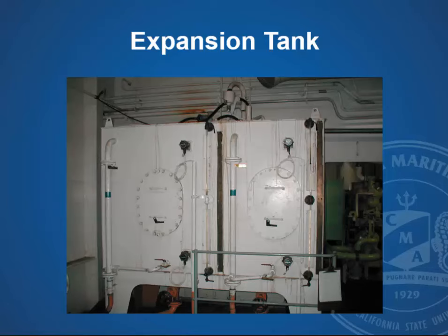But again, this is a primary way that you can determine, when the engine's running, if you see gases coming into that expansion tank in significant quantities, it's most likely a cracked liner, cracked cover.